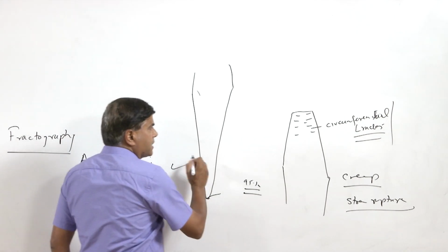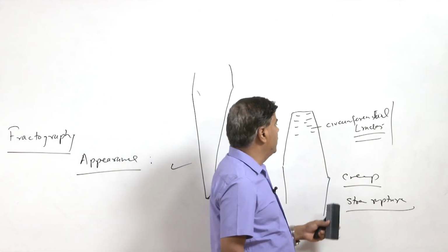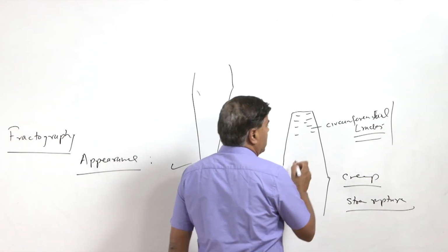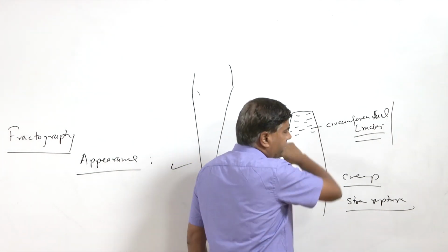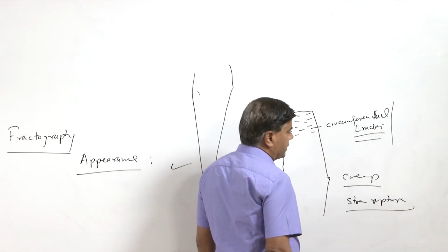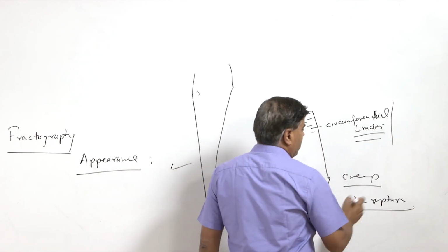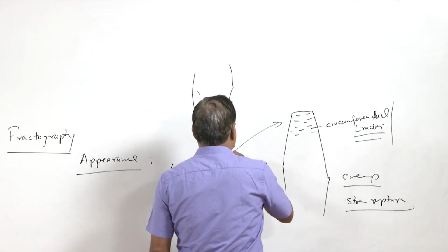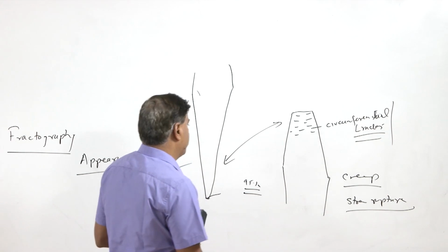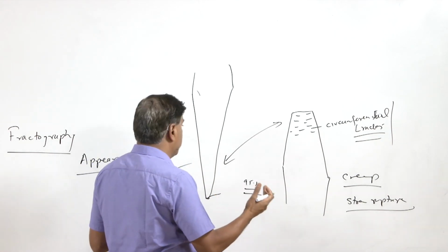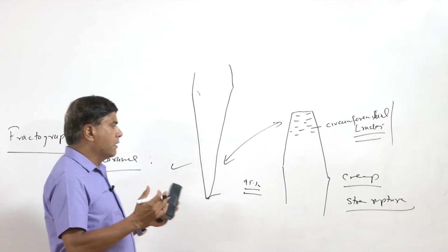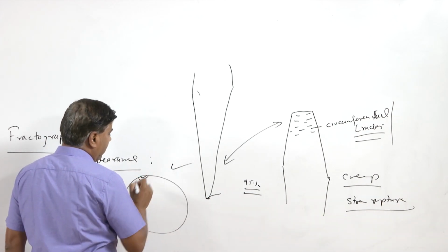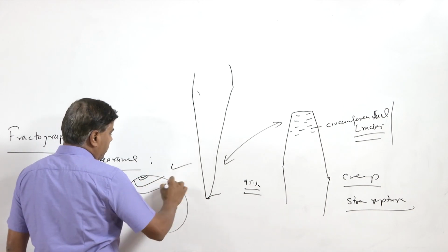That will be this case, and in this case particularly grain boundary sliding is so huge that a lot of circumferential cracks are developed near the fracture surface, which eventually causes the fracture. So, these are the two types of appearances of the fracture surfaces of components which are subjected to creep. Similarly, as I said, under fatigue conditions, somewhere a crack will nucleate and then it will grow,